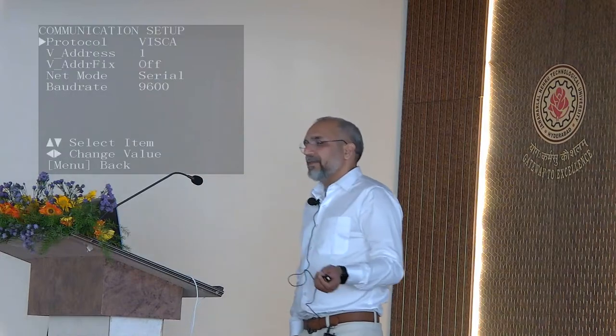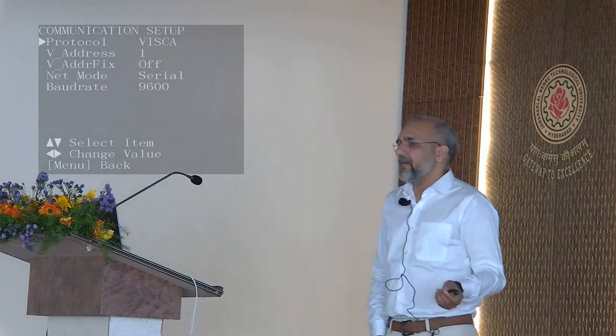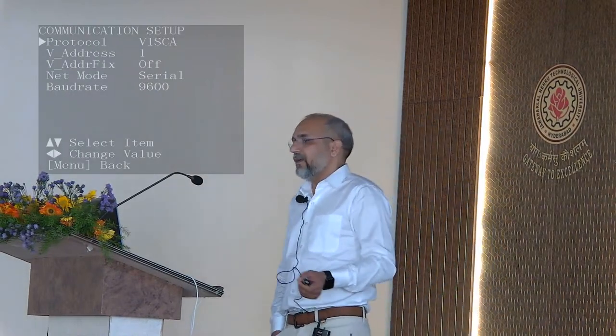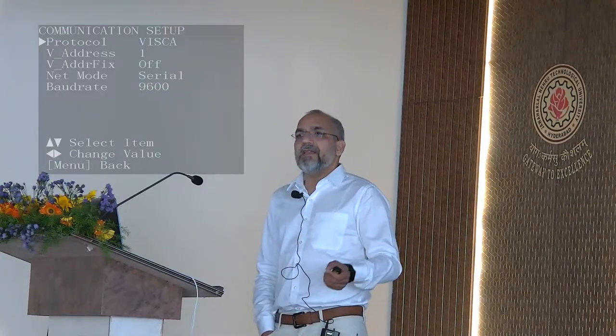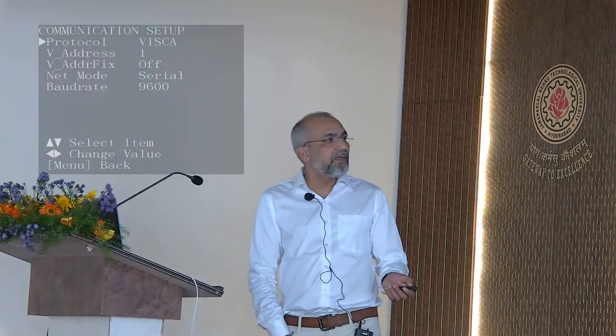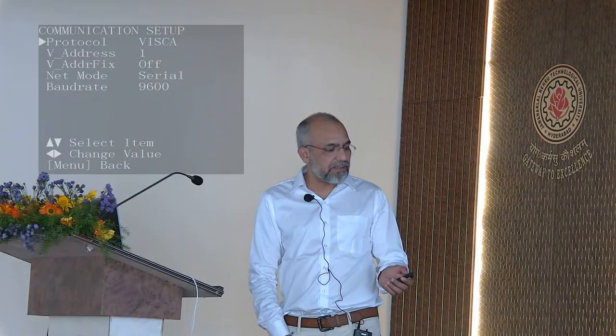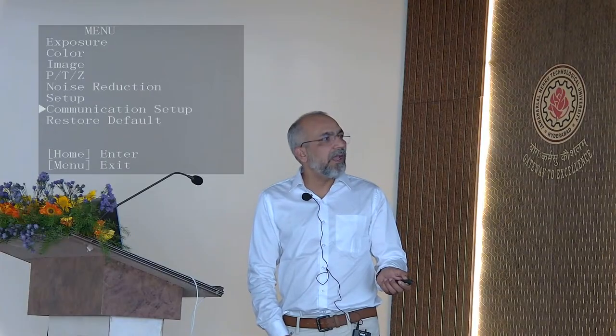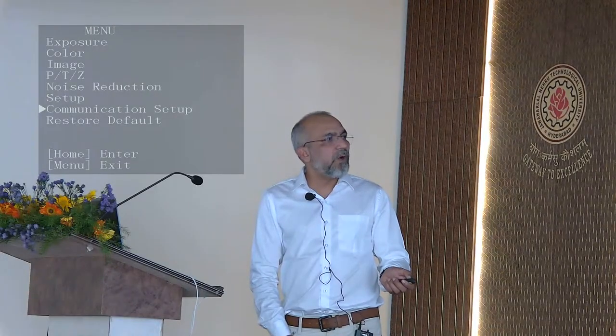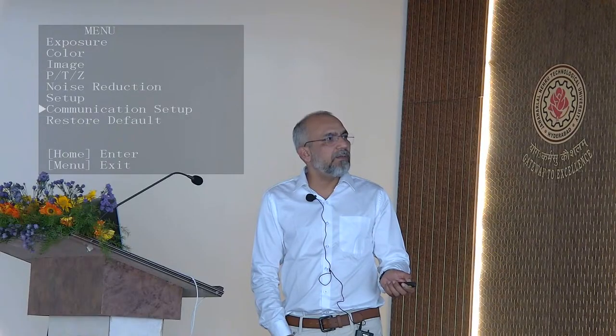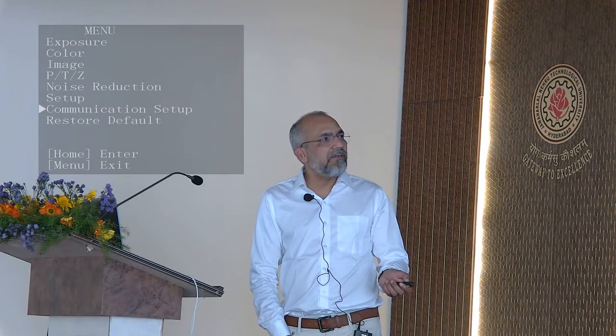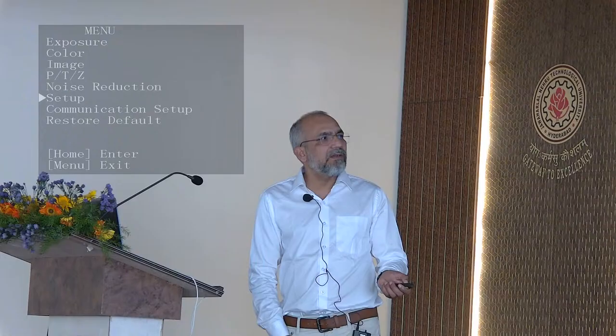And here is the process of how they have done it. First, you have the substrate. On the substrate, you deposit a gold thin film, and then you have the bulk material. So for example, here you have MoS2, and then simply on the top you put a tape, and on the bottom you have this gold film, and finally you have a monolayer on the gold.